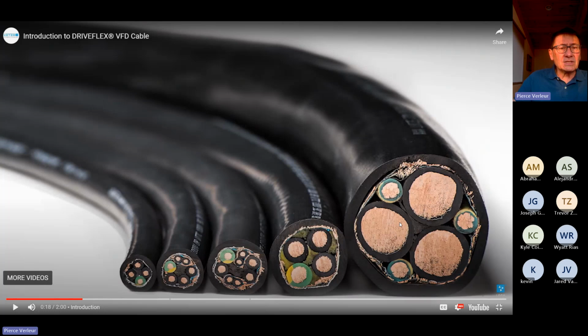That pulse width modulation is pulse, pulse, pulse, pulse, pulse. It's not a smooth sine wave. It therefore makes sense that we might want to consider using a special cable to handle the different waveform. And we're going to present a case to you today why that should be classified as better and sometimes even best practice versus using standard cables.